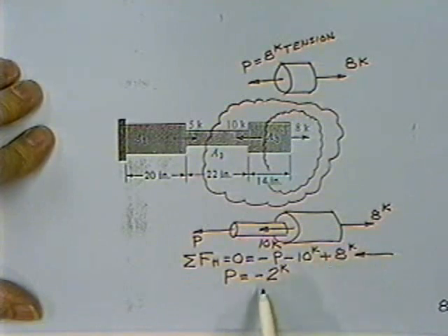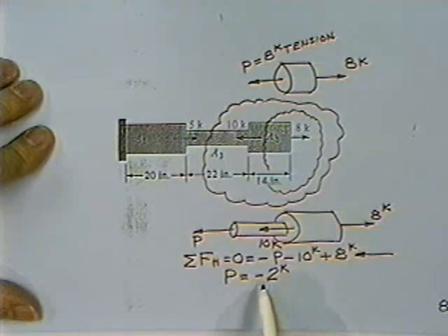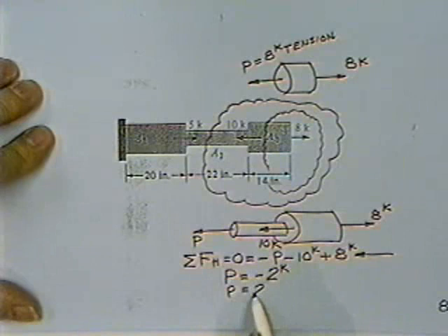But when you start picking things up and moving them on either side of the equation just so you can get an answer, those signs no longer mean the same thing. The minus sign now simply means, I don't know which way it used to be, but it was wrong. That tells you that whatever way you guessed, the arrowhead P is pointing the wrong way. So in our case, we would say that P load is 2 kips of compression.